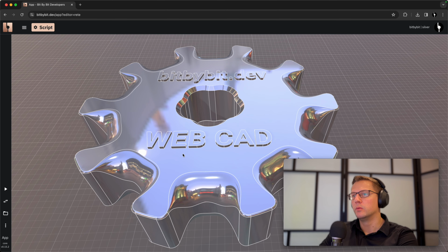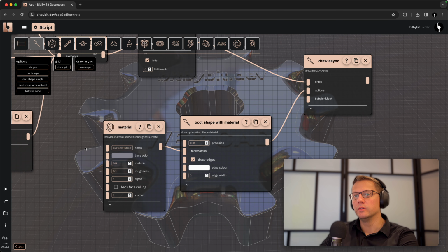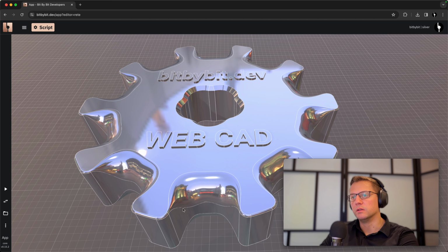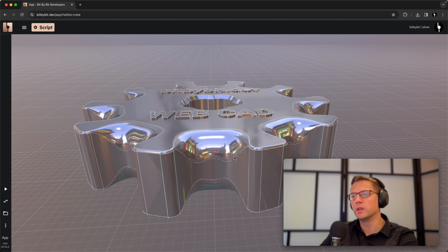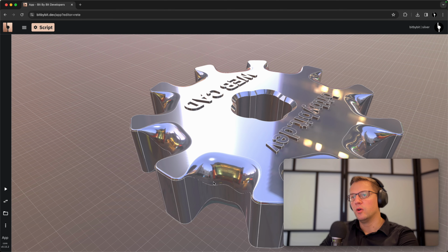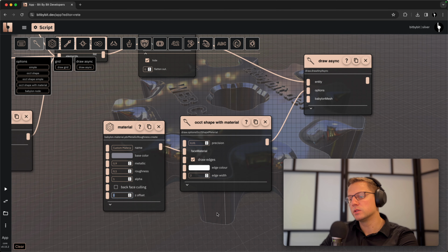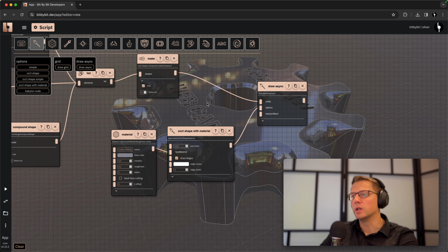Okay, so we have now this shape, we've drawn it, and you can play around with this Z factor. This is exactly what I mentioned previously to you, that if you have it on 0, your face will intervene a little with the edges. So you see that now the edges disappear just a tiny bit because they are overlapped by the faces. But if we just use the Z offset, it's just a parameter on the material that allows you to render geometry a little bit nicer.